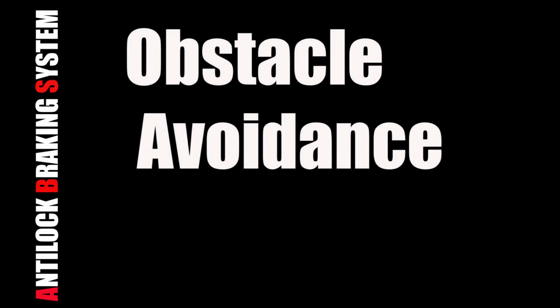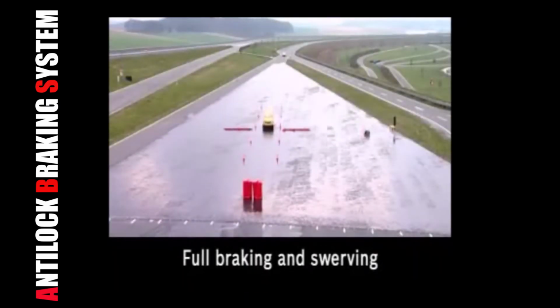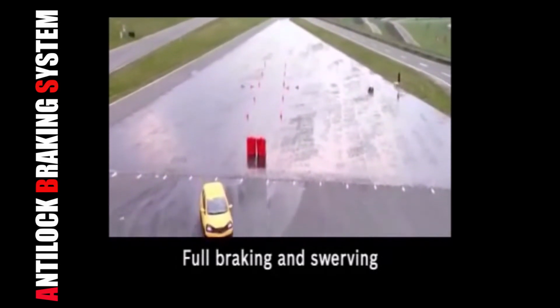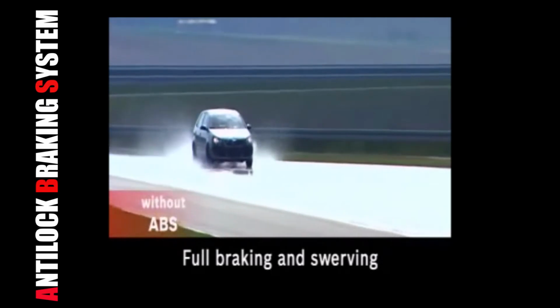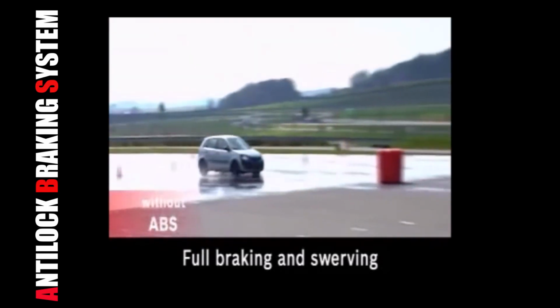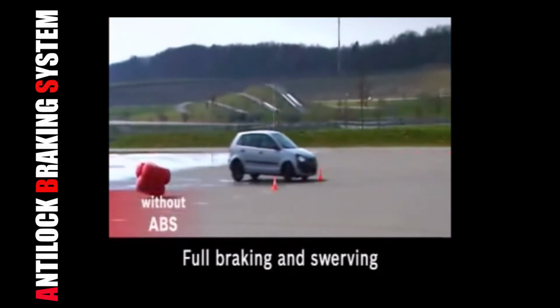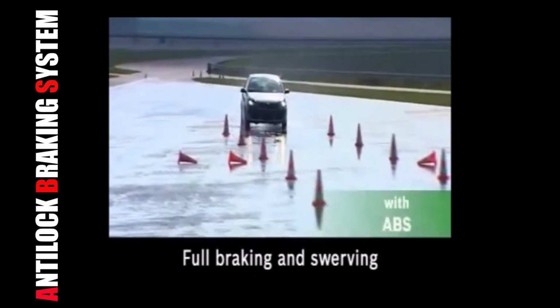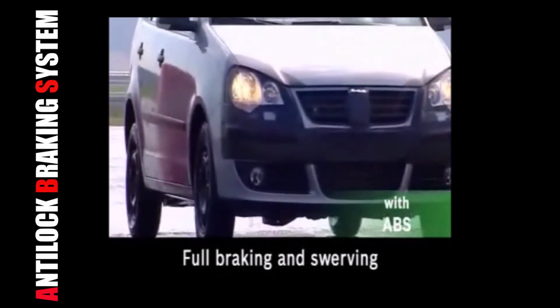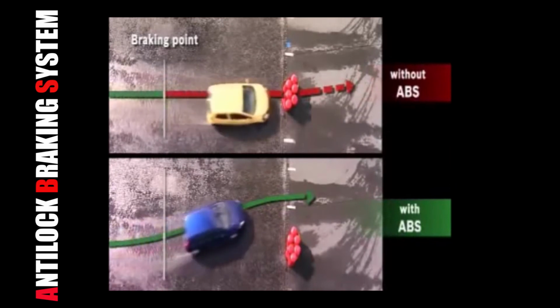Obstacle avoidance. Now this is what ABS was originally designed to do. Here we can see we've got a nice wet road, very slippery, and we've got an obstacle that we have to get around. Okay, so here we have without ABS, hit the brakes as hard as you can, full lock on the steering, and it makes no difference whatsoever. The vehicle continued straight. With ABS, it makes it look like a piece of cake. You still have full steering under harsh braking.